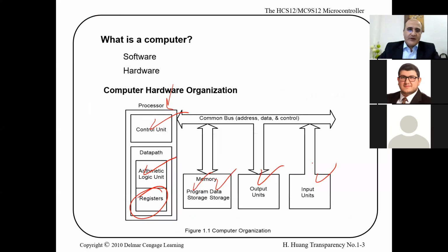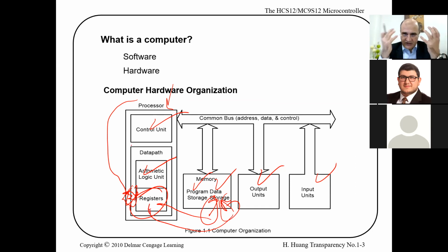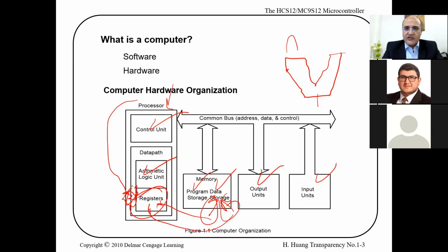The processor has inside it some memory storage locations to hold the operands A and B when I want to add them. Sometimes you cannot add them while they are in the data memory. Sometimes you can, but anyway, usually data is fetched and put in registers. This is governed by the hardware, so the ALU can act on them. For example, this is an ALU, very generic. It always adds register A with register B.